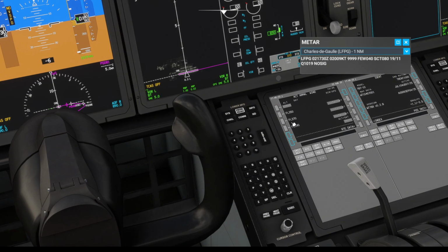Sometimes the flight level is blocked, or we have headwinds or thunderstorms, whatever. So sometimes you have to fly at a lower altitude, and we're flying in an odd level since we're going eastbound. So flight level 380 is most likely not an option. There are some cases where you would fly an even level on an easterly route, which is indicated on your chart, but in most times you can plan on the odd numbers if you go eastbound.